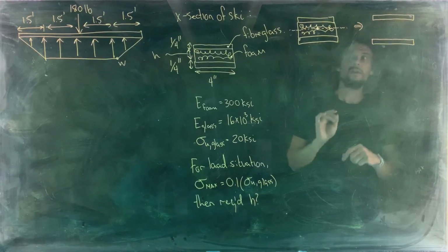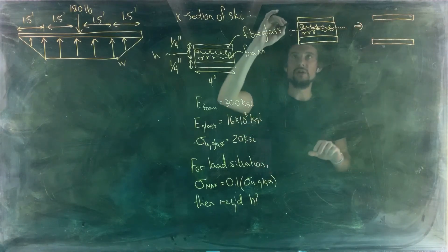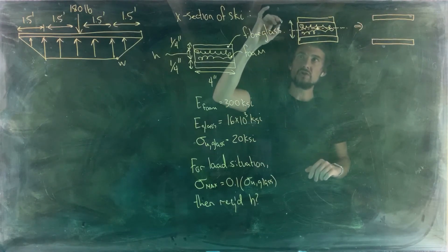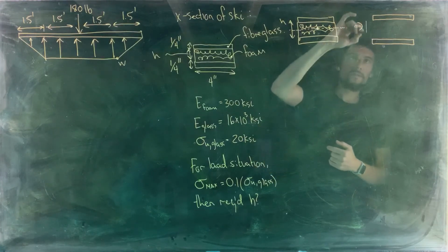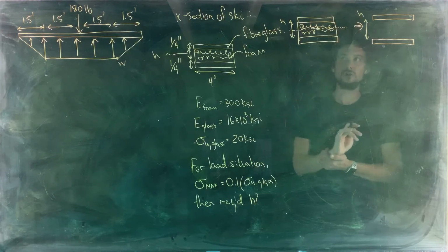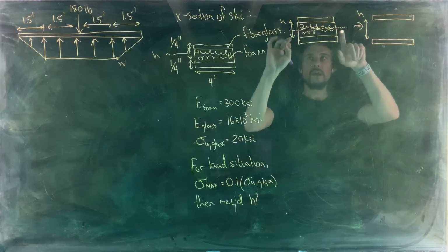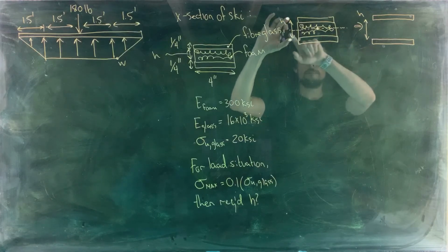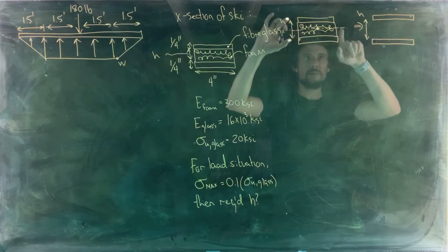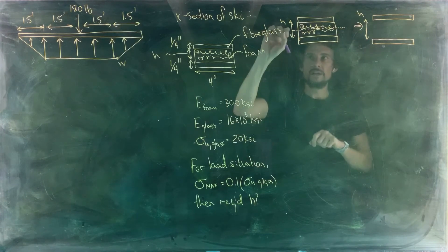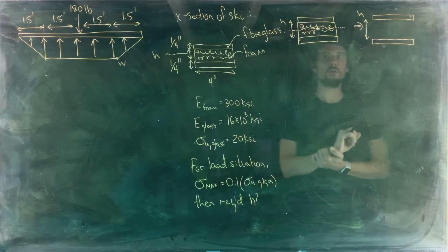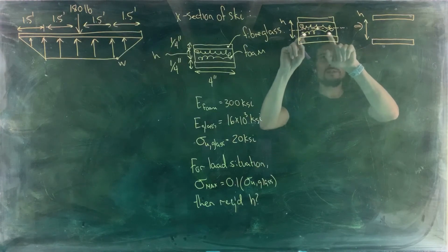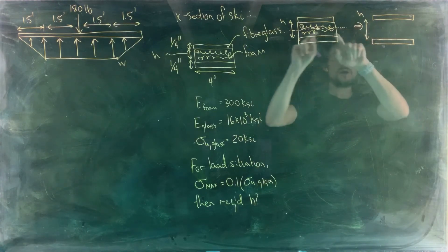Importantly, we are not going to change the overall height of the beam either. This distance is going to remain h. It's very important that you do not transform dimensions that are perpendicular to the axis of bending, because those dimensions affect the variable y in your equation for stress, My over I, and you don't want to mess with those variables.